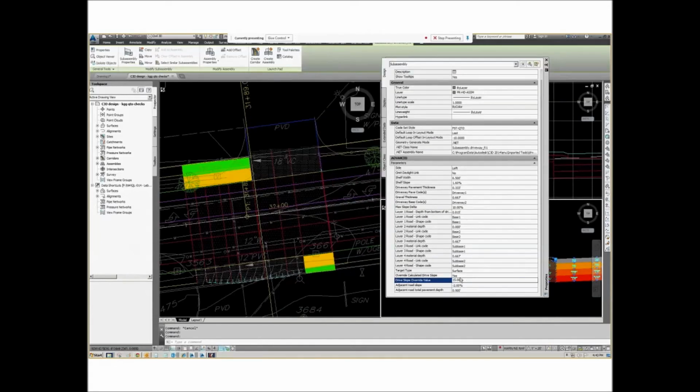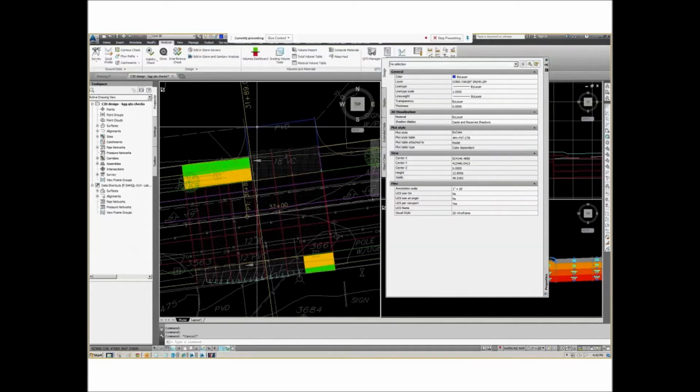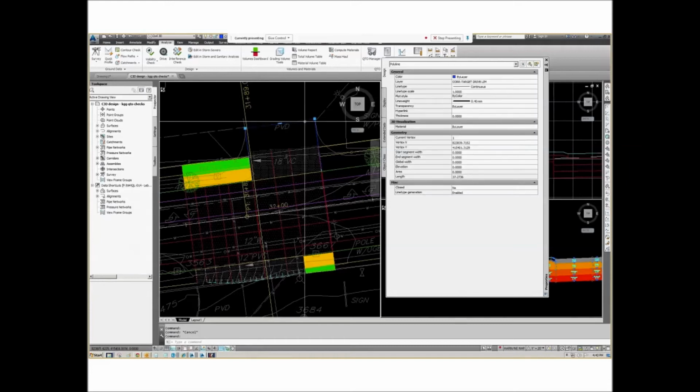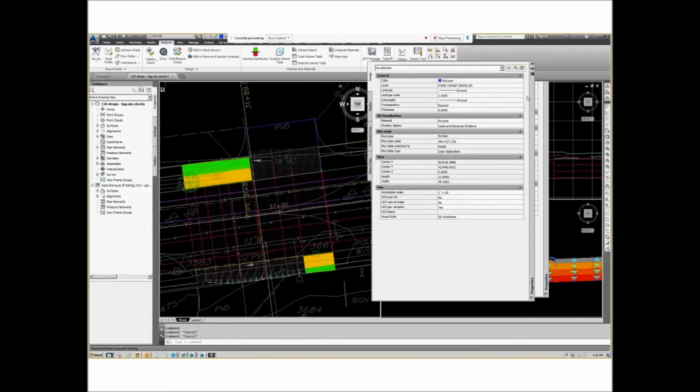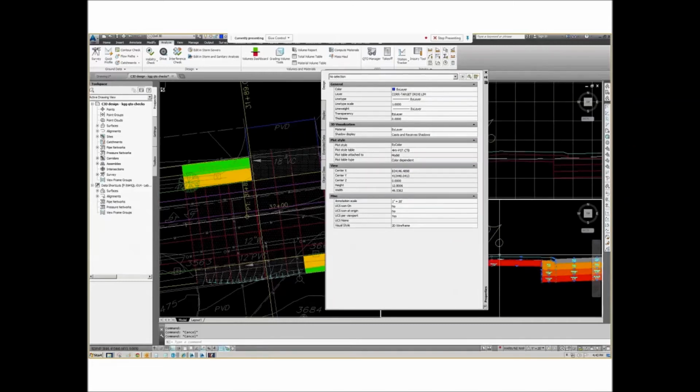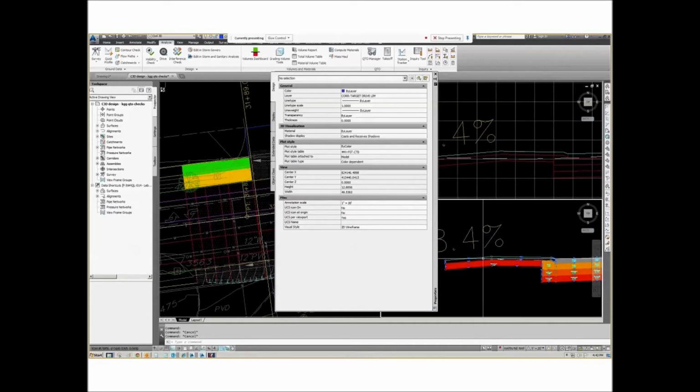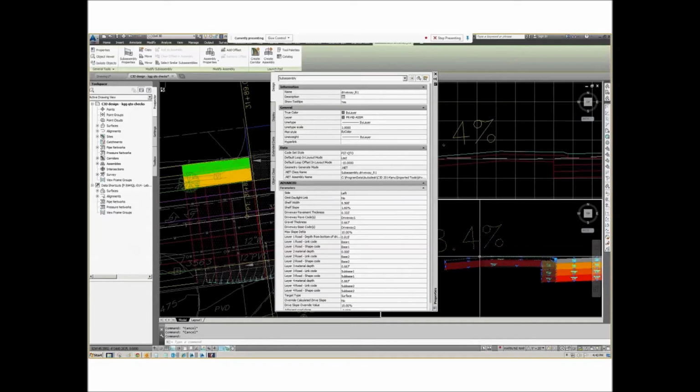Another option is you look at your design with the max delta slope applied, and you look in a driveway by driveway case basis, like this one for example, and say, well, it actually makes sense that we bring the driveway limit up to here. So all you have to do is change the way the driveway daylights, the way it terminates.